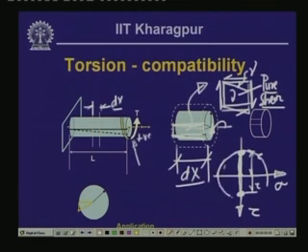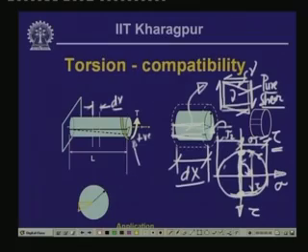then we get the value of the normal stress that will be acting, and this is the value of the normal stress. Maximum normal stress is this, which is sigma 1, and the minimum normal stress is this, which is sigma 2. Now, interestingly, if you look into the values of sigma 1 and sigma 2, both are equal to tau. So, basically due to the application of the twisting moment, the bar is subjected to a shearing stress, and thereby we are going to get the normal stress, which is also equivalent in magnitude to the shearing stress. Only the angle here is 90 degrees. So, the action of this principal stress will be at an angle of 45 degrees with respect to this shear, and that will be the maximum normal stress, which is equal to the value of tau.